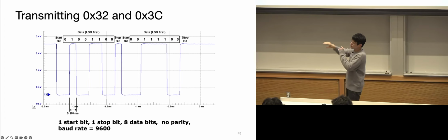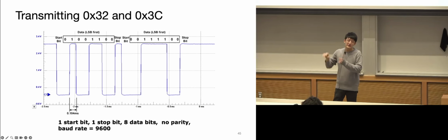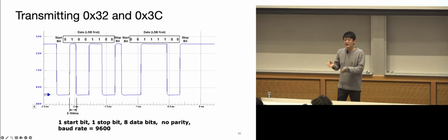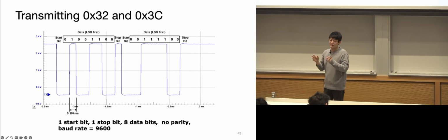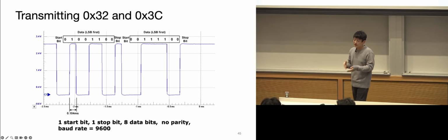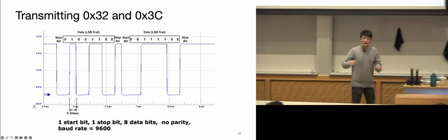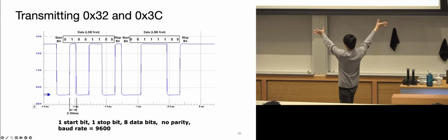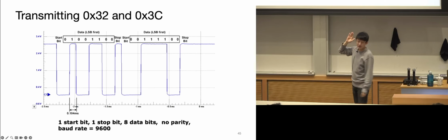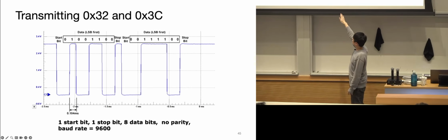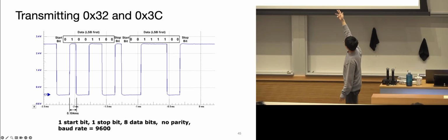And they can have multiple of these data frames coming in, because imagine you're sending a word or sentence. Each of this transmission, or data frame, consists of one character from the ASCII table. So it's going to have a bunch of them coming with very short time gaps in between. And the way we would decide that is just checking on the start bit and checking on the stop bit. In this particular case, there is no parity bit.